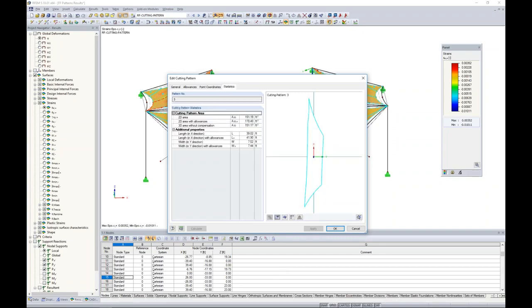The statistics is pretty important to point out. The area of our 3D shape was 151.17 square feet. If we take a look at the area for the 2D shape, after that flattening process has been applied, we have 151.19 square feet. That's almost identical. We're off by 0.02 feet. So again, this just goes to show you that something like the minimum energy method has a very accurate process of flattening these 3D shapes into 2D surfaces, which we can give to our manufacturer.